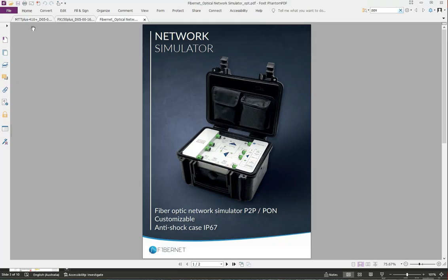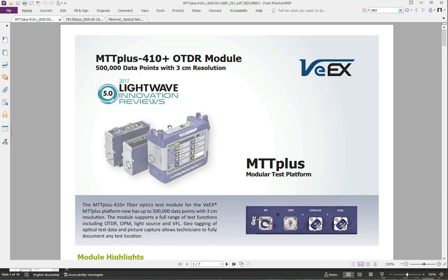So that's the one we'll be using. That's the OTDR, and these are the interfaces on the top panel. So we got the OTDR port for single mode and another auxiliary port OTDR, which could be for either multi-mode or the 1625 filtered port. You got two more ports, the optical power meter and the visual fault locator for testing. So this is quickly the tools that we will be using.